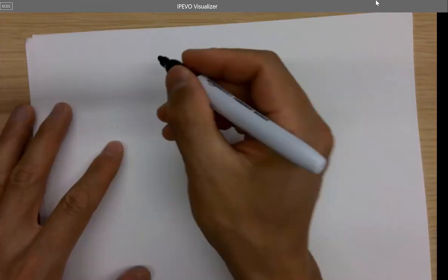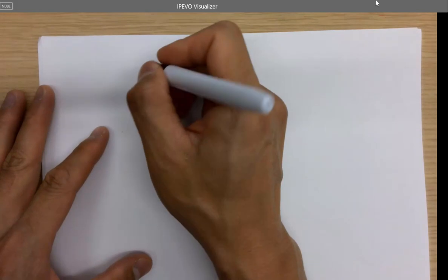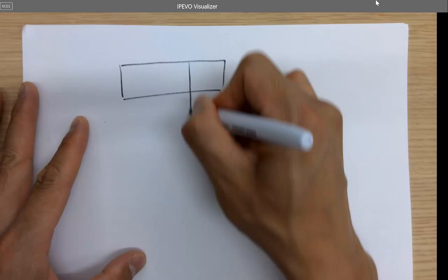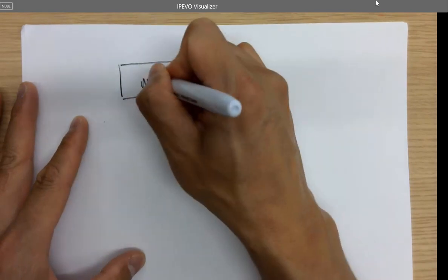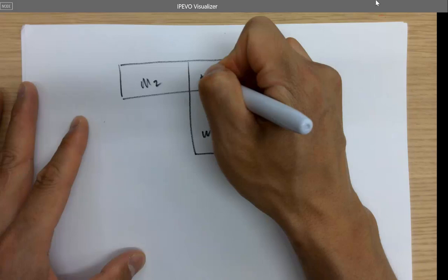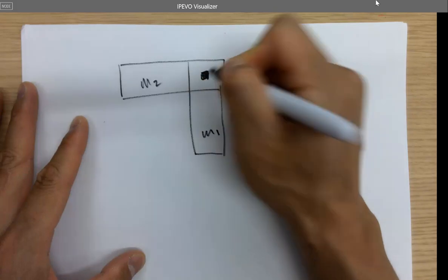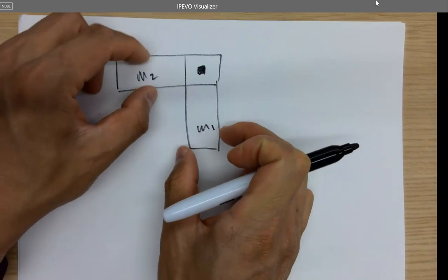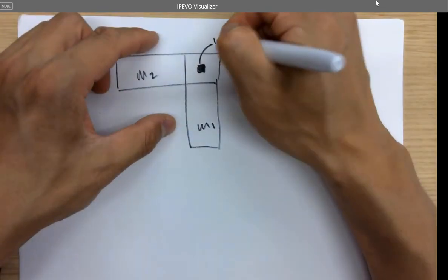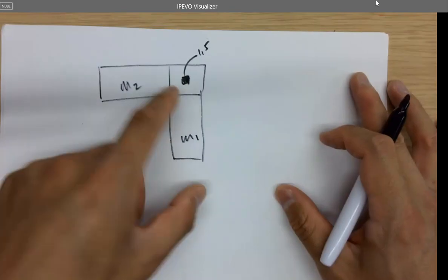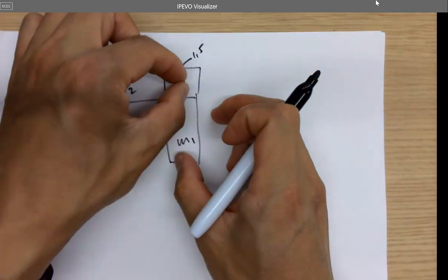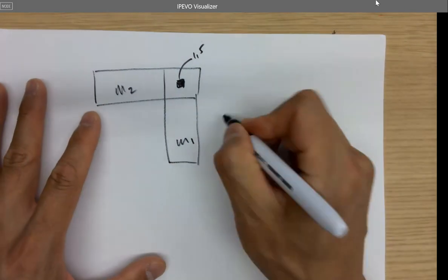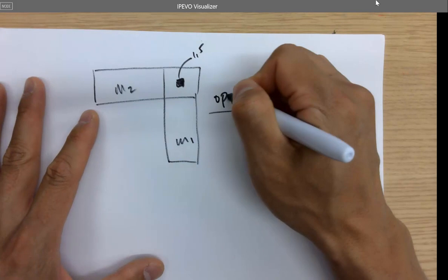So there's an example. For example, I have a bigger, pretty wide metal trace, like metal 2. And you've got a metal 1. That's metal 2. That's metal 1. And here's an overlap, and here's a via. If the metal trace is pretty wide, but the exact via size is 1.5, it looks pretty odd, right? You have a huge metal trace, but a little tiny dot in the middle, which is not really a good design. So this will be optimized.